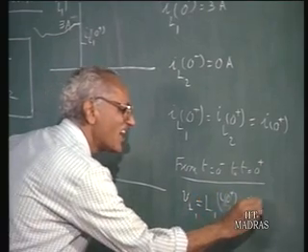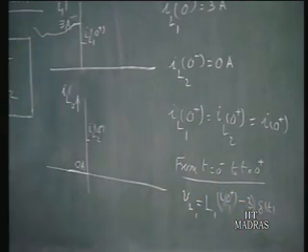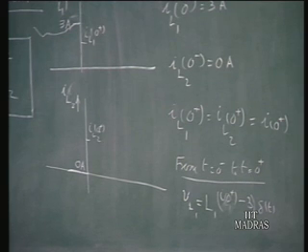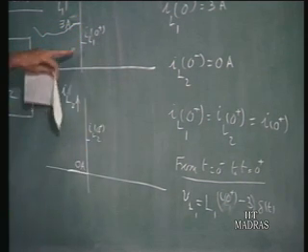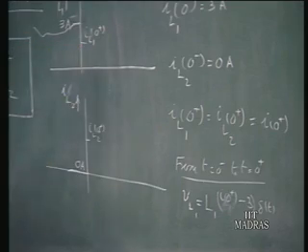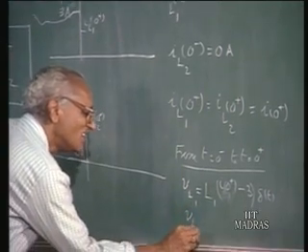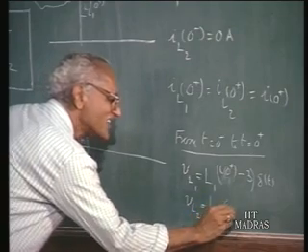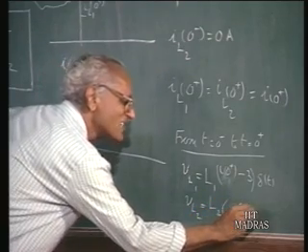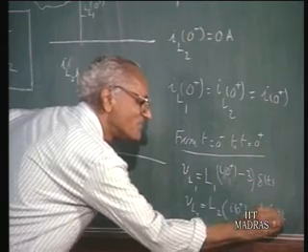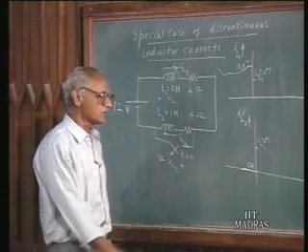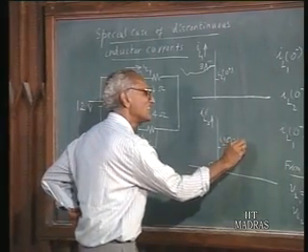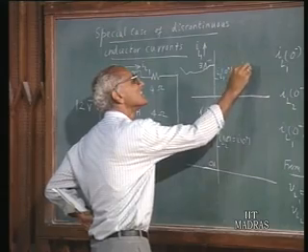So, that is the strength of the impulse. There must be an impulse voltage which is equal to L1 times (I0+ minus 3) times delta t, because suddenly this current has jumped from this to this. So, it is a negative impulse. As a matter of fact, if I0+ is smaller than 3, this is a negative impulse. And VL2 is L2 times I0+ minus the original current, which is 0, times delta t. So, the current in this inductor has jumped from 0 to IL2(0+), which we call I0+.